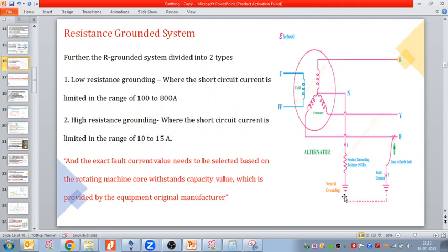And at the same time, flowing through the ground, it reaches the neutral point, the neutral grounding, where it gets a return path. Here we have the NGR as well, and it flows back to the system, to the source. Current has a nature that it flows towards the low resistance path, and it tends to flow towards the source as well, right?